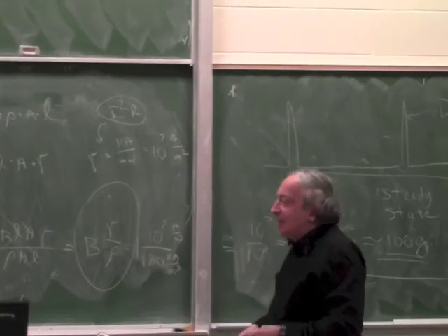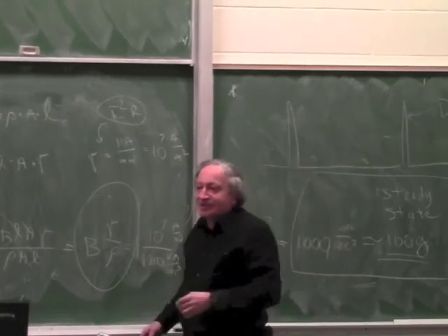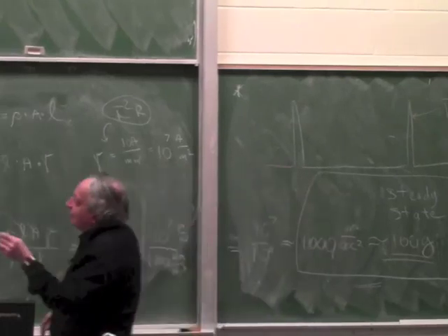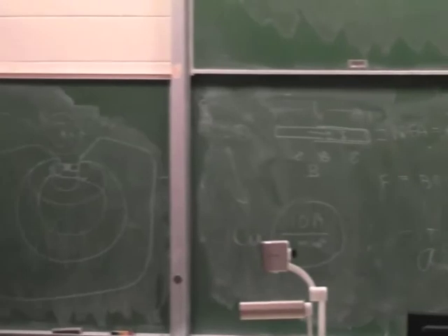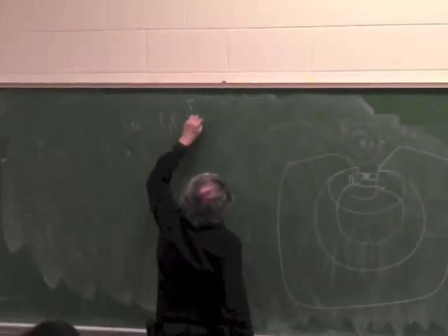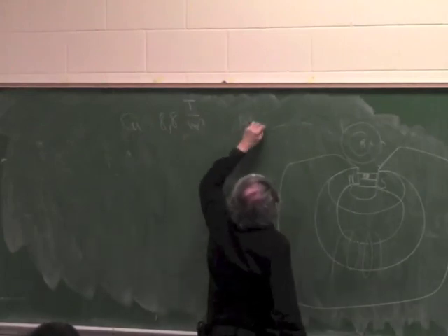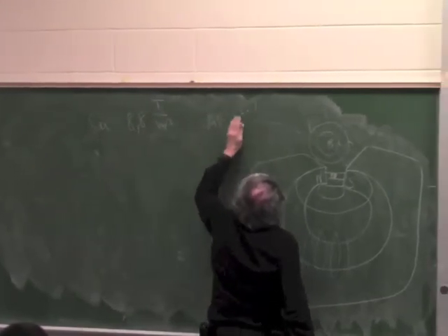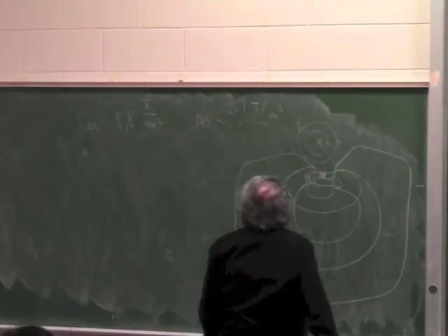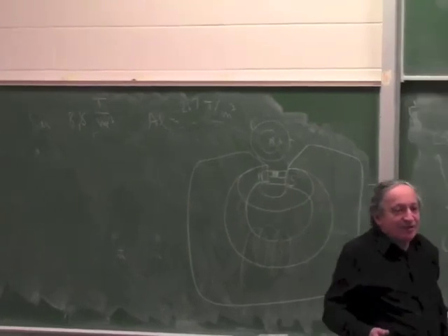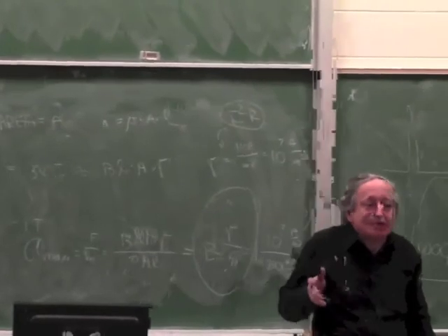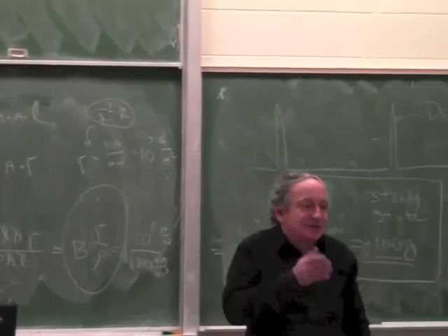Basically, aluminum weighs about a third of copper, because copper is 8.8 roughly, so copper is 8.8 ton per meter cube, aluminum is 2.7 ton per meter cube. So roughly speaking, aluminum is a third of copper, but the thermal conductivity is maybe 60% of copper. Depends on the alloy, depends on many things.